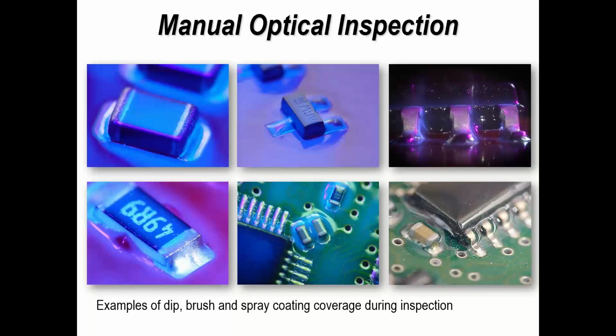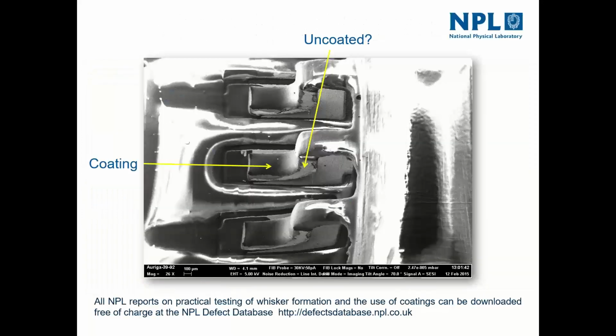And that's why you see in this photograph some optical images under UV light, and more about that a little bit later on. But you can see how the surface tends to fluoresce, and that's one way in which we inspect coated boards.